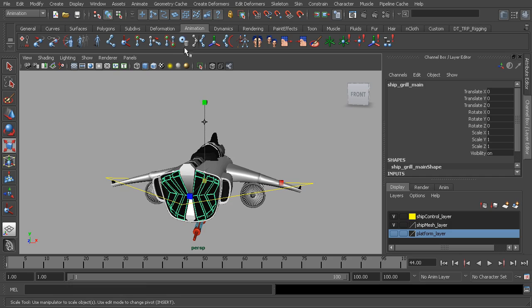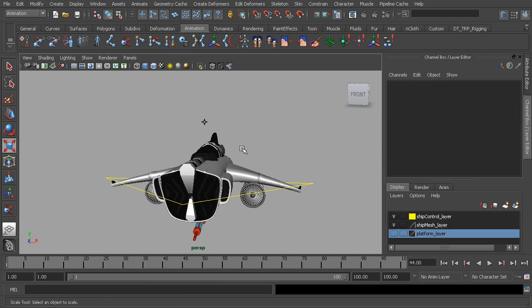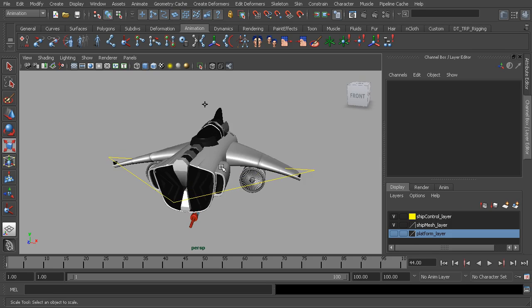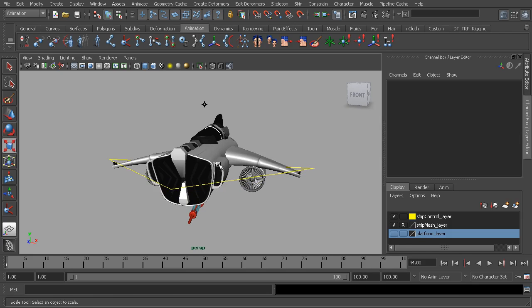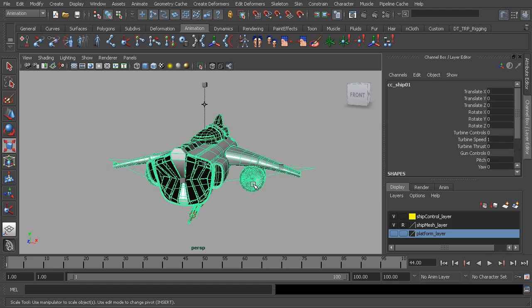Great. All right, so at this point, we can make sure that our mesh is not selectable. We could do that a few ways. Remember, from the status bar, you can turn it on from here. But I'd say a faster and more reliable solution would probably be to do that from the layer. Just go ahead and reference it. The reason why is when you restart Maya, of course, the mesh toggle at the top will also be reset. All right, so you can just go ahead and reference the layer and not have to worry about that.